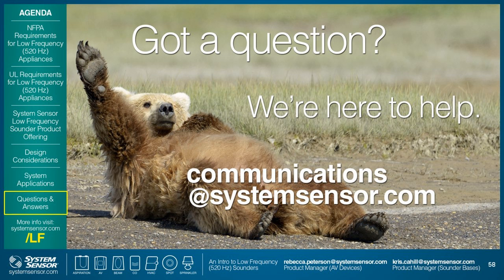Okay. Chris, I think this is related to the synchronizing together, but the question is worded a little differently. I just want to make sure we've got it covered. Is there a way to interconnect sounder bases? The SR version uses an interconnect wire. The S version can actually be synchronized through the panels. So they are both synchronized, it's just different means. So the S has a little bit more, a nicer way to do it, a simpler way to do it. Okay, all right, very good.